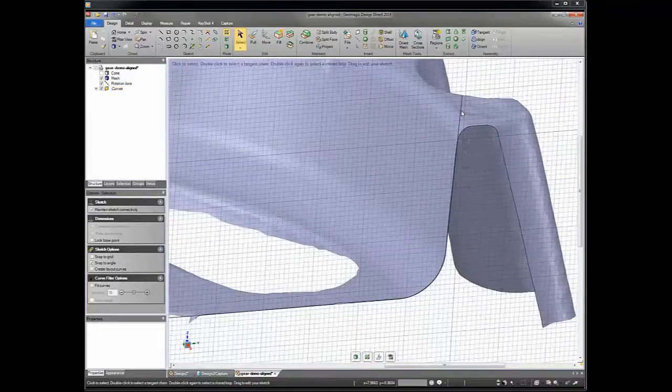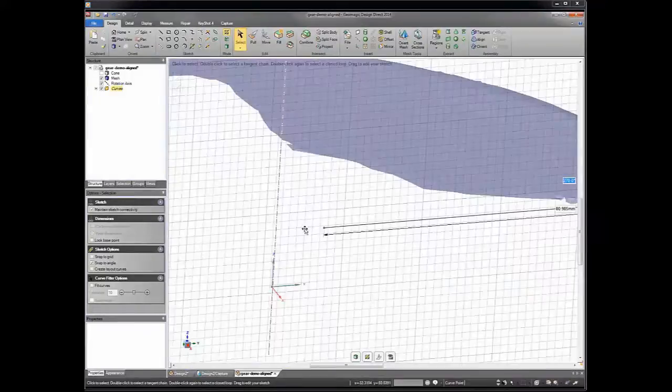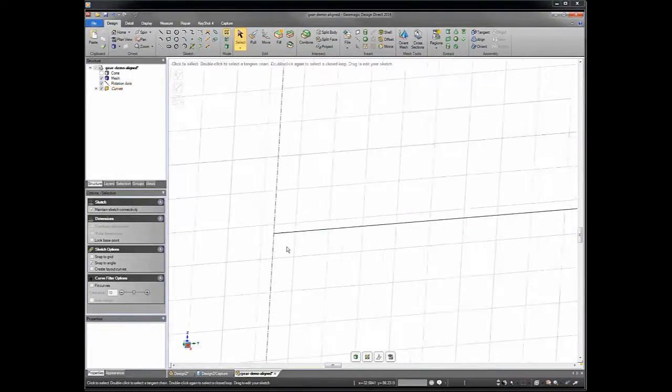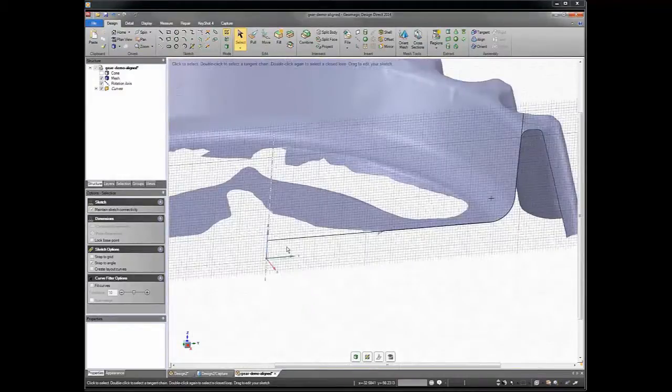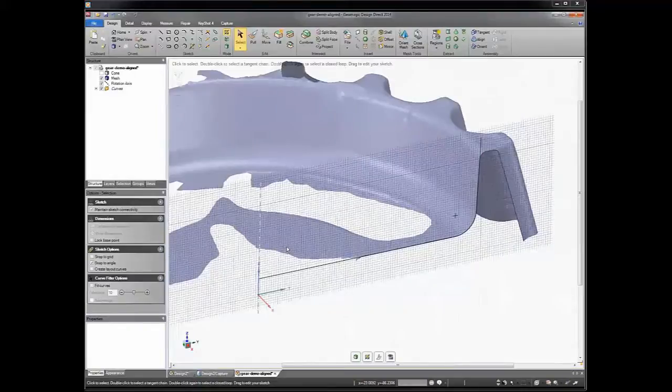So that way I know it's not going too far. Same thing here. What I might want to do is extend this line, and it keeps it on that trajectory. And I might want to snap it to this line. Okay? So you don't have to just create sketches in solids directly. You can take a stopover at the sketch phase and add or change the extracted sketch profiles.